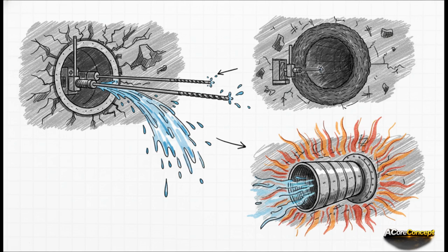We aren't just dealing with cold water. Engineers regularly hit active geothermal anomalies where rock reservoir temperatures exceed 230 degrees Celsius. You need highly specialized heavy-duty ventilation protocols just to keep the work environment survivable and stop your concrete from degrading.